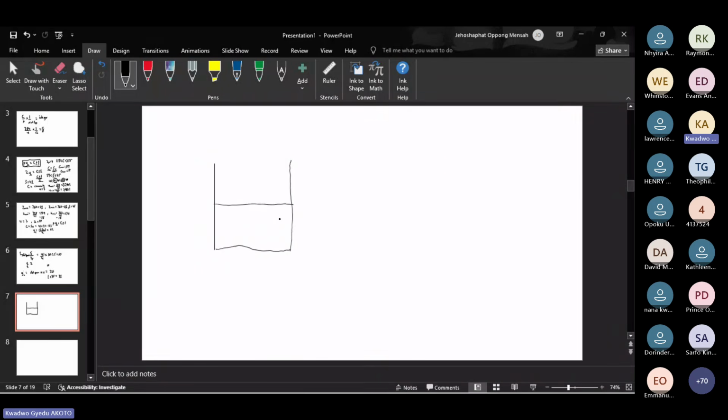If we have a 2-layer slot, then we must have 6 conductors per layer, because the number of rows is equal to 3 and the number of columns, U, is equal to 3.